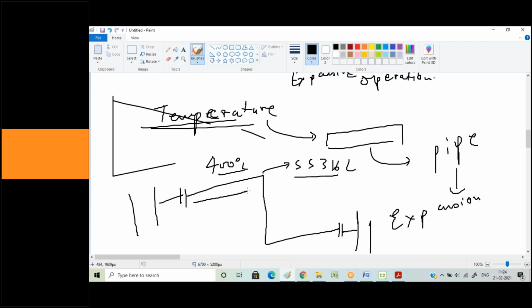Now when this expands in this direction or in this direction, obviously because these two points are fixed, the pipe will only move in the other direction because it can't move in this direction. If it moves in this direction, this will actually hurt your nozzle over here, which would be the point of failure and the point of concern where we get the nozzle loads for. Always when a vendor gives a nozzle load, it is always for this particular point.